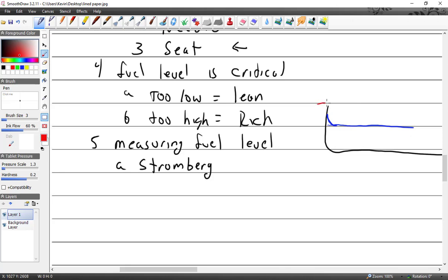So you're going to take your depth gauge, and it has a little pin that comes down. So you're going to set this all the way across, and you're going to measure this. And as you get down here to the surface, you're going to come down a little bit more, a little bit more, and right about the time you get right next to the surface, bam, fuel's just going to jump up on there. It's just all of a sudden, whoosh, fuel goes up. And now it looks like this needle is halfway under the fuel, right? But it's not. It just jumped up on it. So that's your correct reading. Stop, take a reading, do it 3 times.